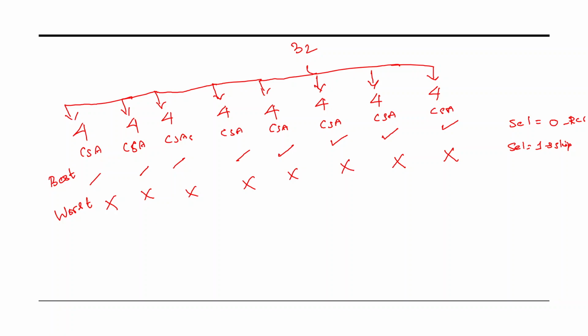Through the carry skip adder, we have understood the operation of a carry skip adder and how skip logic allows faster carry propagation. We have compared it with the ripple carry adder and carry lookahead adder. In the carry lookahead adder, the hardware complexity is much larger, whereas here it is much less complexity in the hardware, the area part. Speed wise, moreover, it's the same.